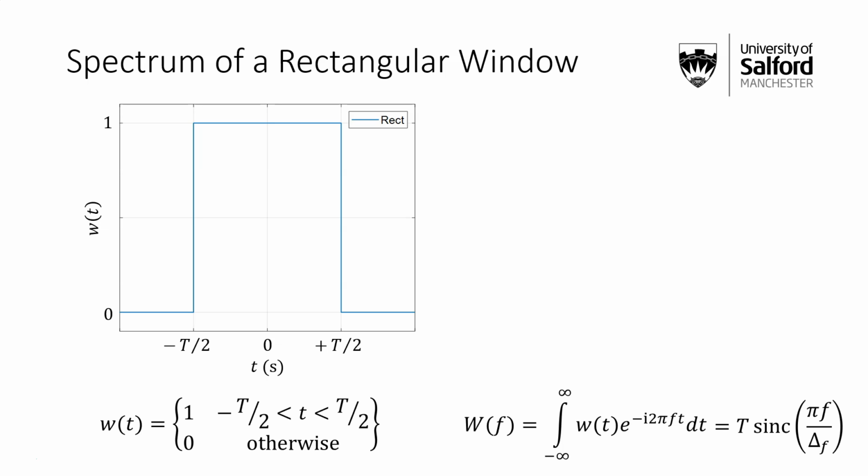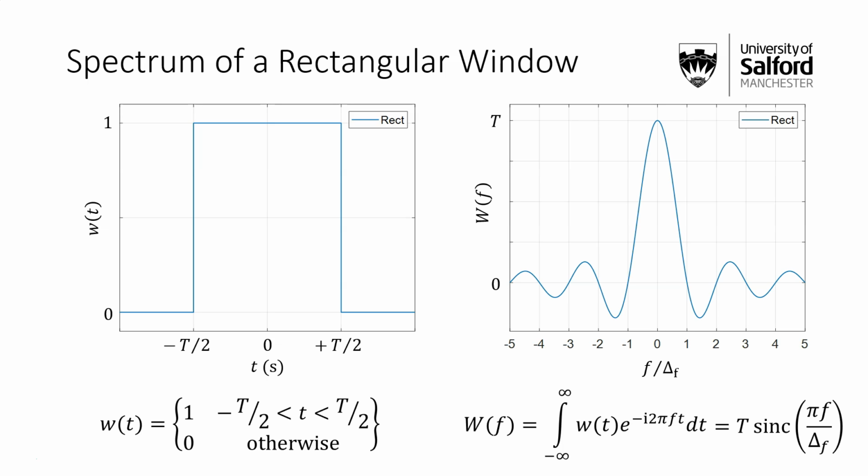It's something called a sinc function. And this looks like this. It has a peak at 0, so it's going to smudge, but it's going to keep the frequencies centered around the frequency that they should have been. So we saw that in the original graph, but it's going to smudge them out to other frequencies as well. And so it kind of attenuates, so it's going to smudge less and less as you get further from the main peak, but it is still going to do something.